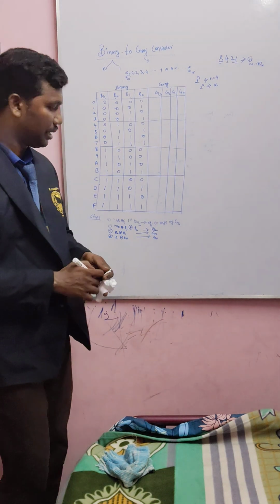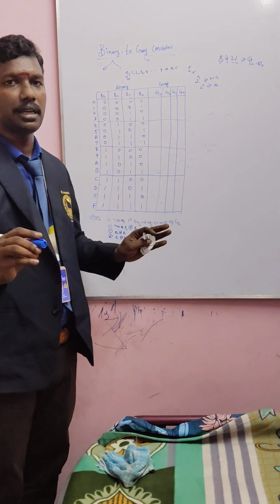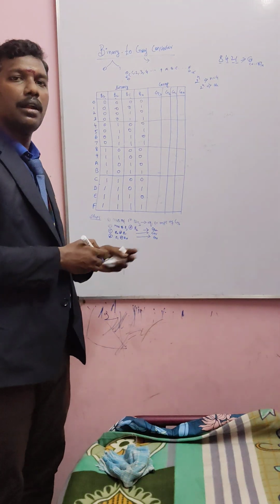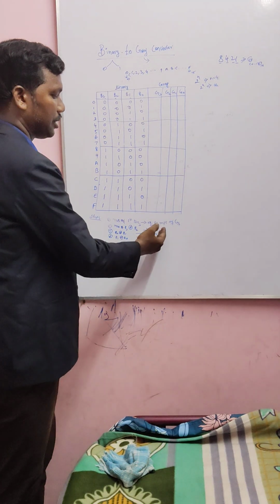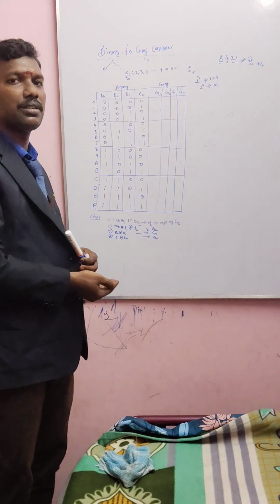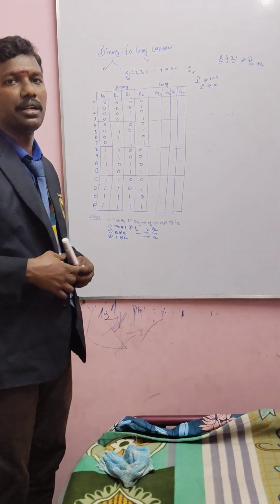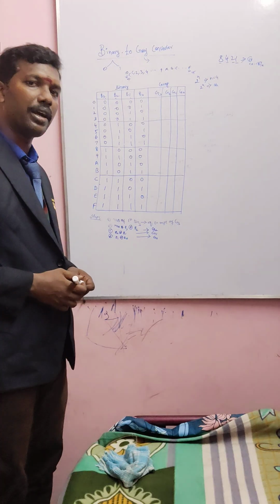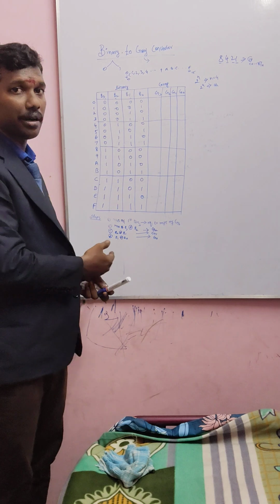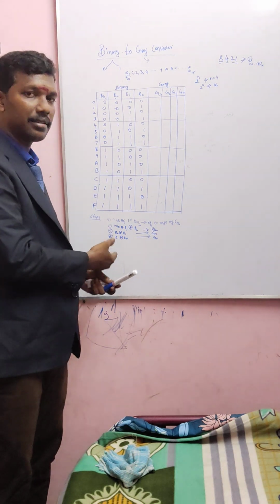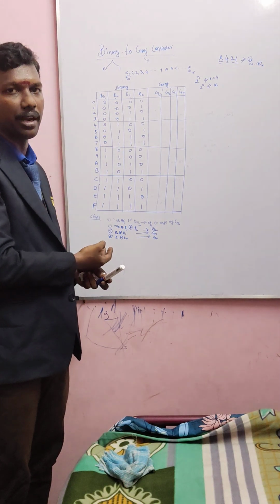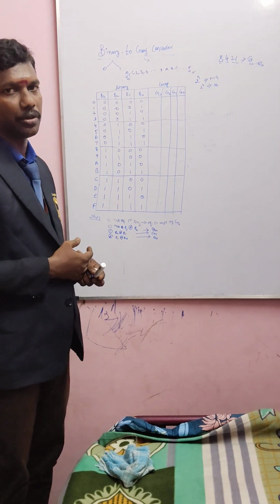So now you can understand the same information, we did not change it, but we have a procedure. The first will be the same, and the second onward will be the XOR operation of the next immediate neighbor bit. So we can get G3, G2, G1, G0. This way we are going to fill the boxes, and once it's converted, you make those primary numbers, that is min terms, to be found and put in the K-map and find the logic diagram also. Okay. So what we are doing is how to convert binary to gray. I am giving the proof, explanations and steps for all 16 combinations of 4-bit binary to gray, not just a single value. The total will be shown to you, right?